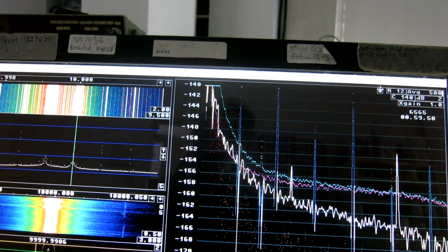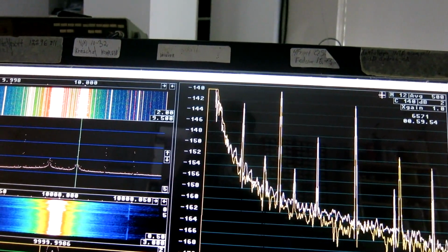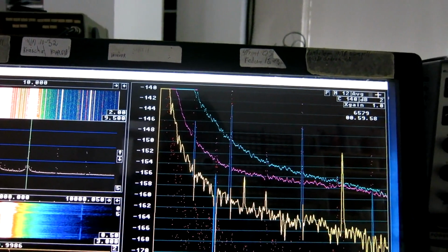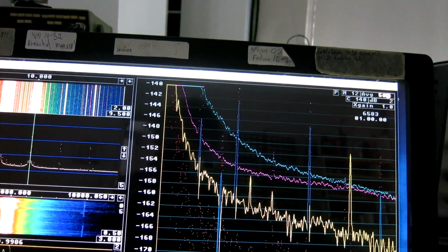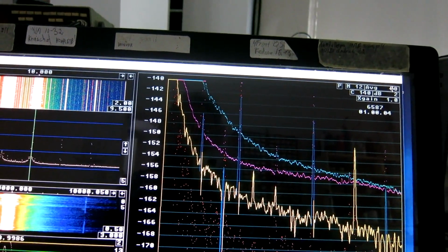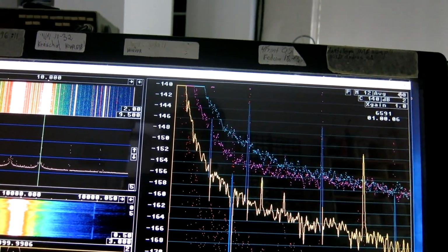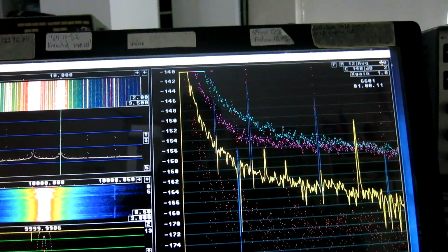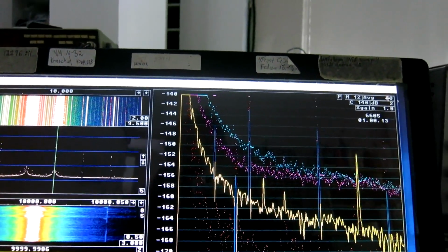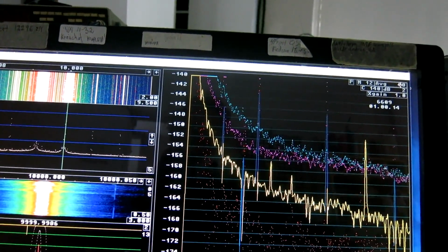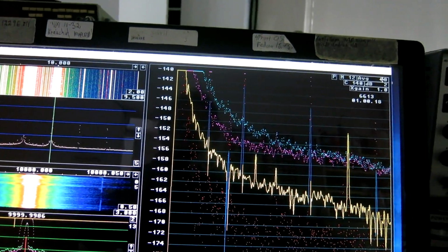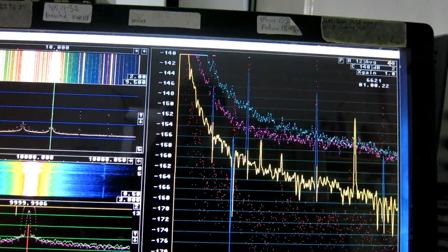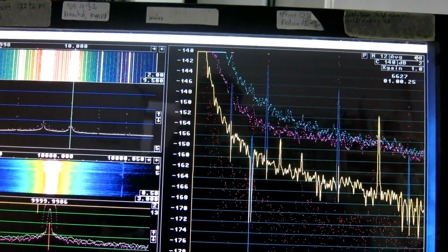And if I go for the phase noise, this is 500 spectra, and now I look at the latest 50. So oscillators are unstable. That is part of the phase and amplitude modulation that I have of the system. And as long as it's not correlated, it just makes the time I have to wait for a stable correlation spectrum longer.